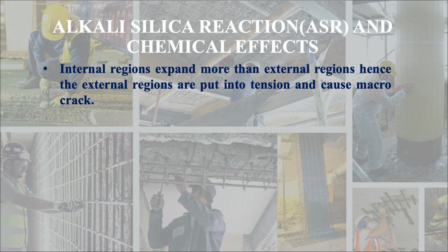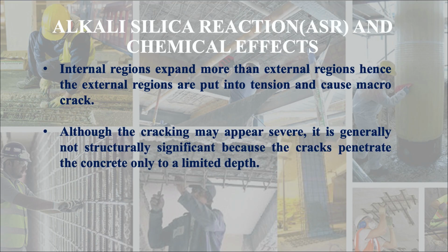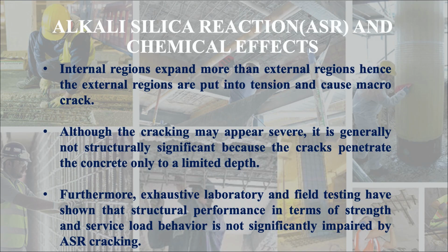Internal regions expand more than the external regions, so that the external regions are put into tension and cause macro cracks. Although the cracking may appear severe, it is generally not structurally significant because the cracks penetrate the concrete only to a limited depth. Furthermore, exhaustive laboratory and field testing have shown that structural performance in terms of strength and service load behavior is not significantly impaired by ASR cracking.